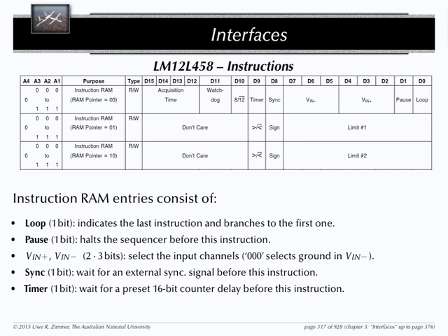Now, they're very simple instructions. So don't get disheartened. Very, very simple instructions. The first 2 are indicators to the sequencer which runs in there. You know what a sequencer is in a CPU? Controls which instruction comes next. Right? You also have a sequencer here. You have to determine which instruction comes next in your AD converter. Now, the information for the sequencer here is quite primitive. No, you don't have a conditional jump or something like that. Don't have a conditional branch.